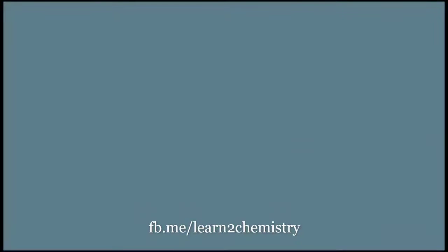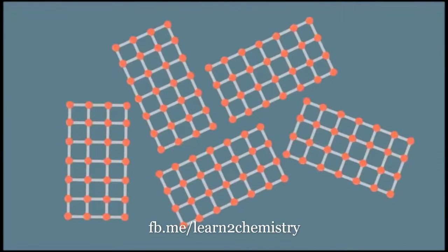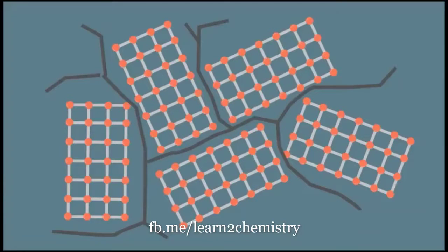In metal, the atoms are arranged in groups. These groups are called grains. These are evident when you look at a zinc-coated surface, or what is known in the industry as a galvanized surface. These grains can work both in favor and against the steel. They can increase the ductility of the steel, but where the grains join, the grain boundaries, are areas where impurities collect.